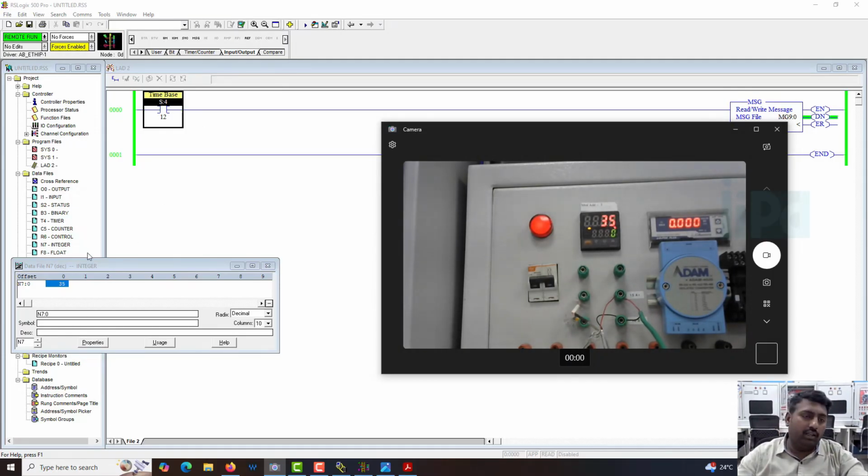So you have to remember one thing. Modbus is a request and acknowledge protocol. So when you are having more than one device to read data from, then you have to think about the round trip time. It has to request data from each device, so it will take time. So half a second for this device. Let's say you have 20 devices. So it takes 10 seconds completely to read all the 20 devices once. So you have to remember that while you are doing the Modbus programming.